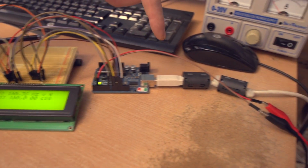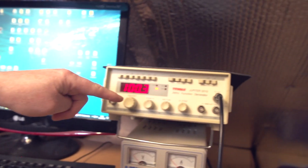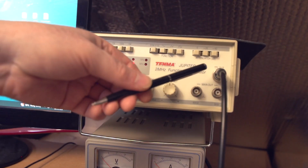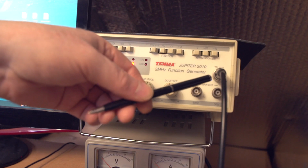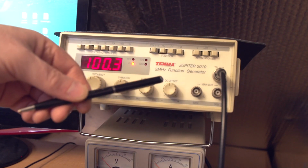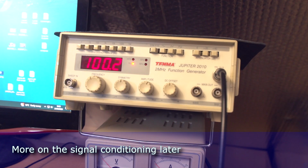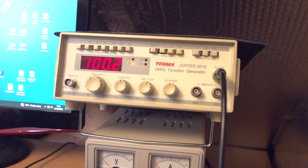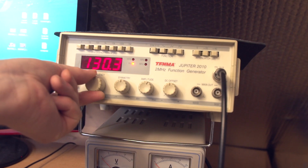Coming through these cables here, through these croc clips here, that's going up to the signal generator, and we're coming out of the TTL output. And the reason why we're coming out of the 5V TTL output, square waves in other words, is because we've got no signal conditioning yet going into the microcontroller here. And I can adjust this just here. I can adjust the frequency to whatever we want.